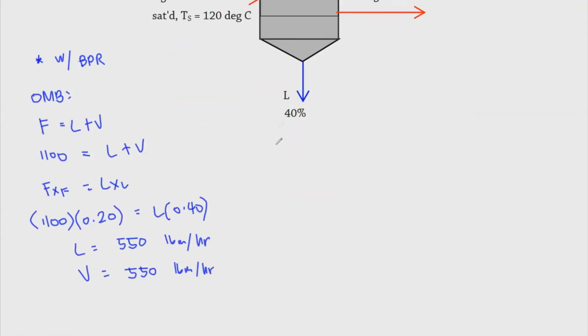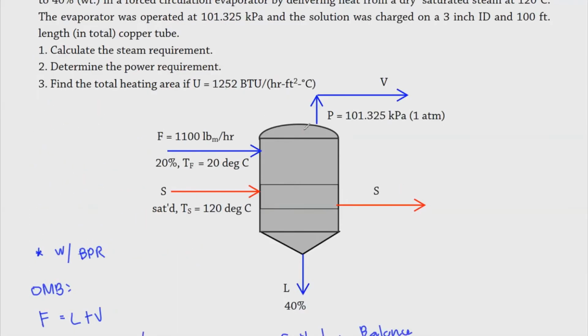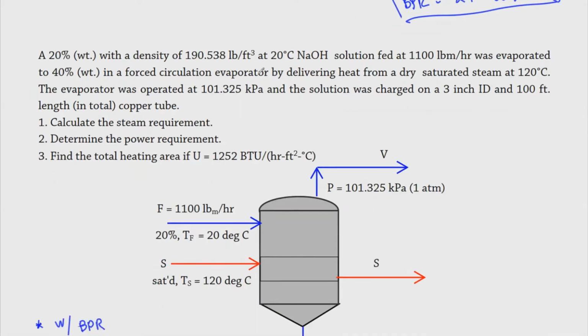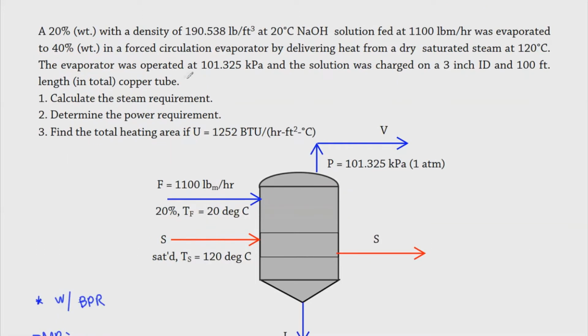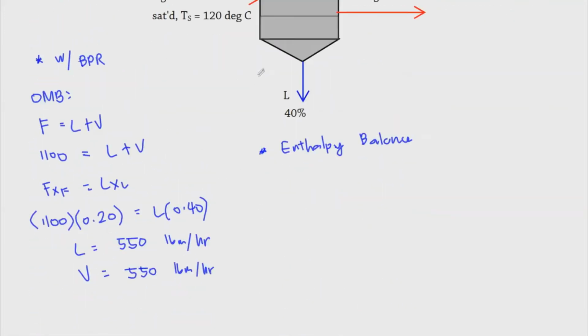Before, I used to solve for a heat balance wherein I actually used the energy balance. Now we proceed with enthalpy first, because that's basically how unit operation should be done. And as I've said before, you should be using this only when you have enough data or information. If you look at this problem, you might say that I don't have enough data because we don't have something like a heat of solution for the feed, for the liquor, so we don't have them. Well, that's true for this